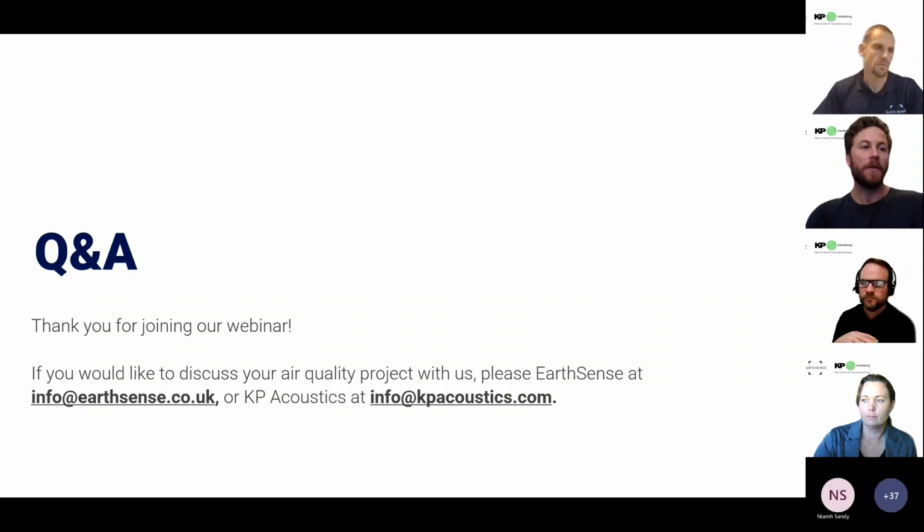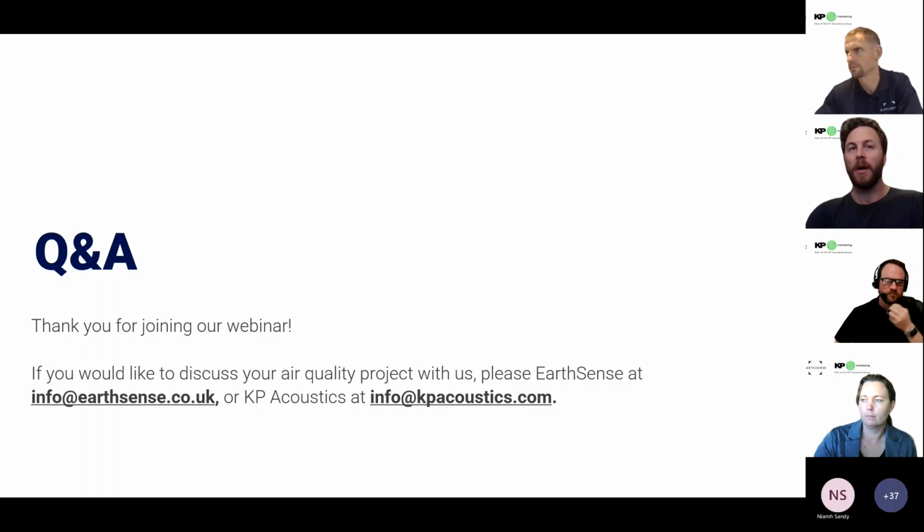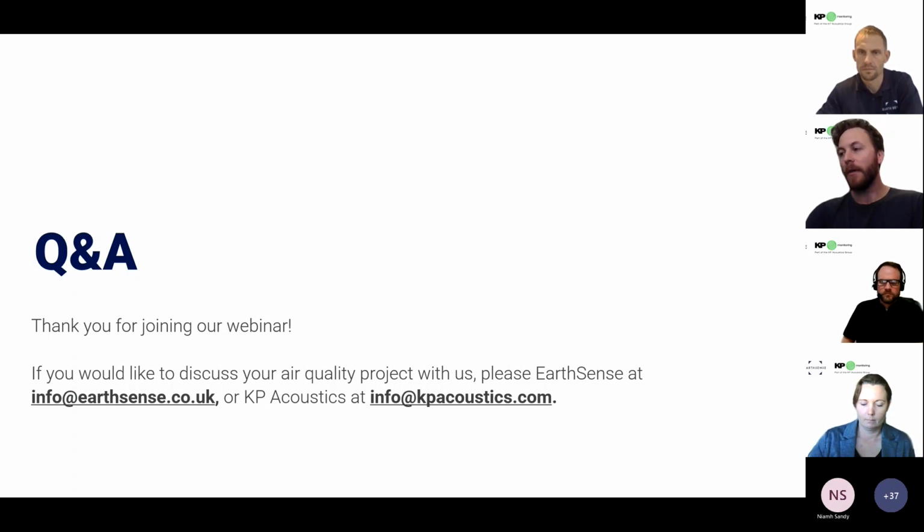Yeah, so that's a big thing with optical systems. Historically, they have a challenge because they would read moisture or water droplets as a particulate. There's two elements. We have algorithms in place to try and remove for that. We're also measuring temperature and humidity, and we're adjusting for that on the fly. We don't see massive problems in fog events, so we don't get very large readings, and we've shown that across the period.